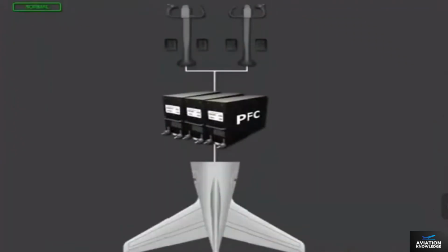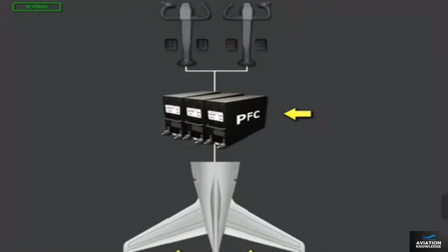In the normal mode, the airplane pitch control characteristics are similar to conventional airplanes. The control column input commands the PFCs to generate a pitch maneuver where the rate is dependent on column displacement. The PFCs automatically position the elevator and stabilizer to generate the commanded maneuver. The PFCs also constantly monitor airplane response to pilot commands and reposition the elevator and stabilizer accordingly.